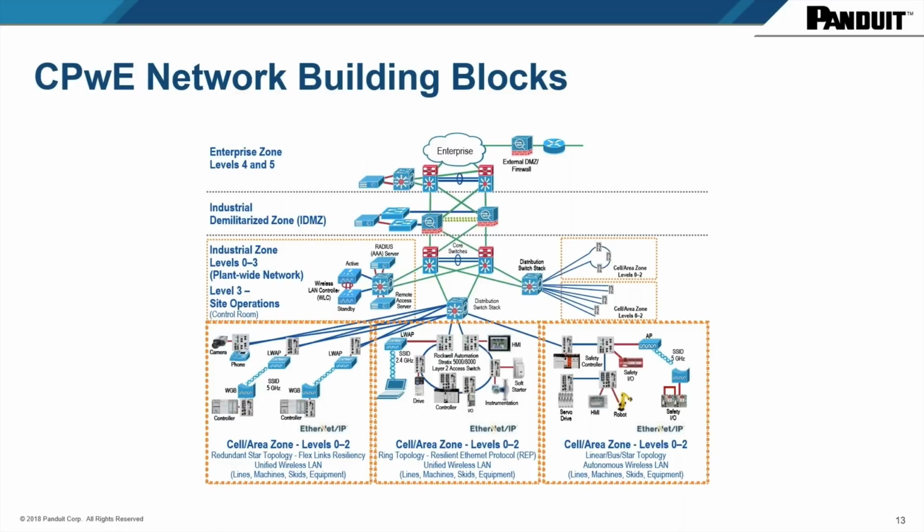So when you look at level 1 in this architecture, you find different cell areas. Each one of those cell areas is independent and runs totally autonomous, but the data that's shared from cell area 1 to cell area 2 has to be shared across very dedicated lines. In this architecture, you'll see that there is a point where we have a distribution switch, collecting all the input coming in from cell area 1, 2, and 3.